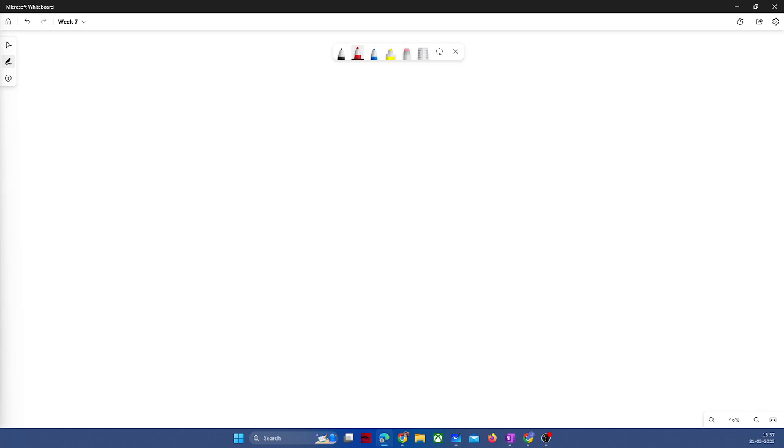And anyway, if you have a converter and it is mentioned that it is lossless and you know the voltage relationship, at any point of time you can say that the current relationship is the opposite of that. So if V naught by V in is equal to N times D, let us suppose in a forward converter, then you can say that I in by I naught is equal to N times D, given that your converter is lossless.